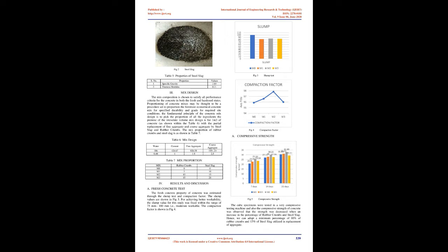Kadab et al., 1999, concluded that mixtures may be made up of CA and FA employing a ground tyre. Supported its workability, an overall volume of 50% may be used. The strength data developed, compressive and flexural, in their study shows that the strength is systematically reduced by the rise in rubber content. From a practical point of view, because of the severe reduction of strength, rubber content shouldn't exceed 20% of the overall volume.